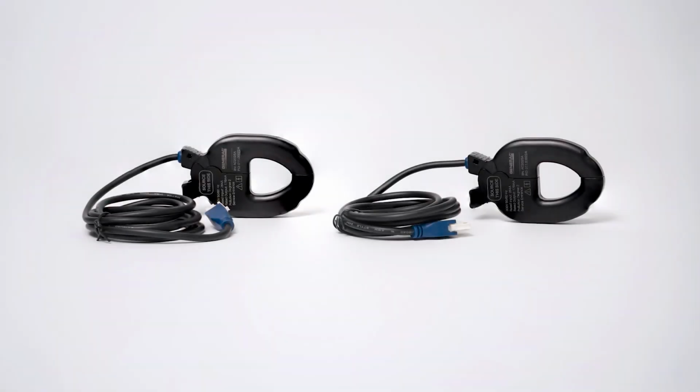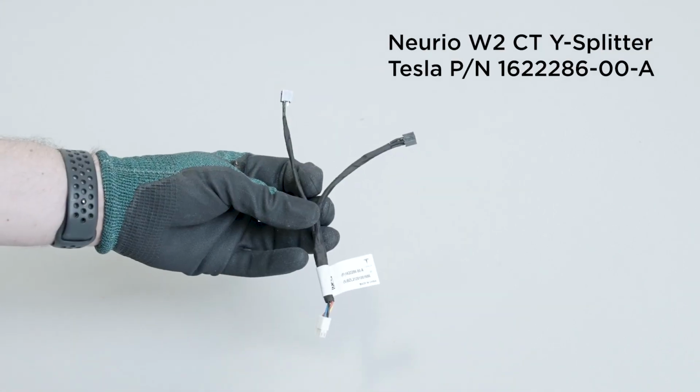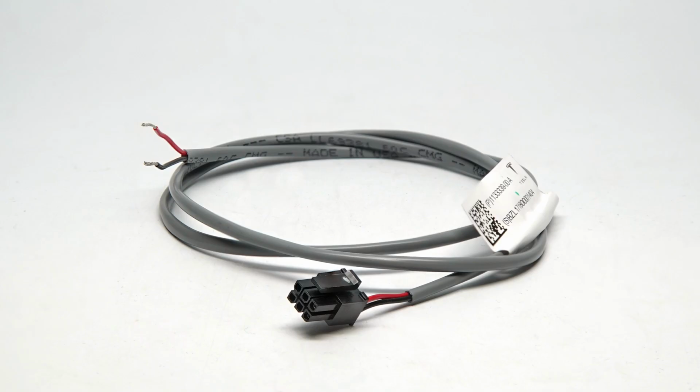If monitoring individual loads or solar production, Y-splitters can be used to connect multiple CTs of the same phase to one port on the meter. A remote meter can communicate with the site controller over a wireless connection. Alternatively, it can be hardwired with an RS-485 connection.